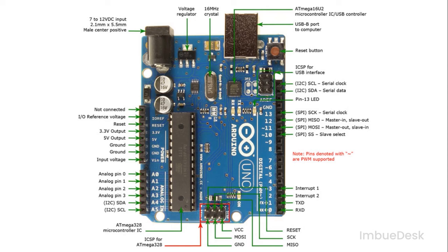You can see the note here, that is all the PWM pulse width modulation pins are denoted with the symbol tilde. Pulse width modulation is the process in which we modify the width of the pulse so that the final power will alter. For example, if we want an LED to glow fully, we give 100% pulse width and we can decrease that to 90, 80 and so on even to 1% to make the LED dimmer and dimmer. That is the use of PWM.